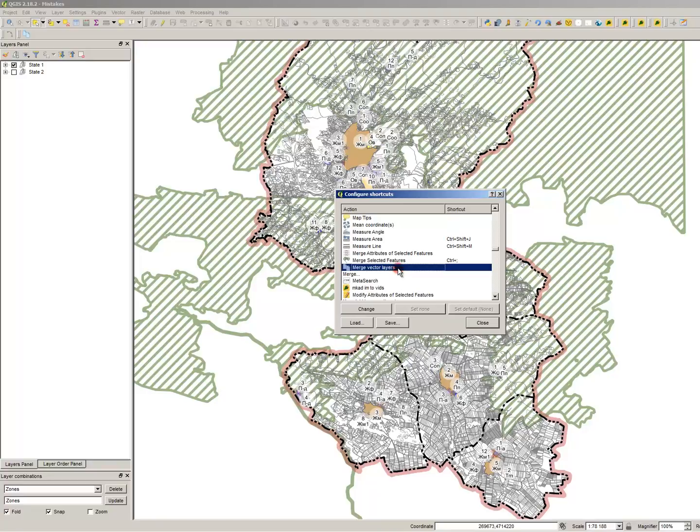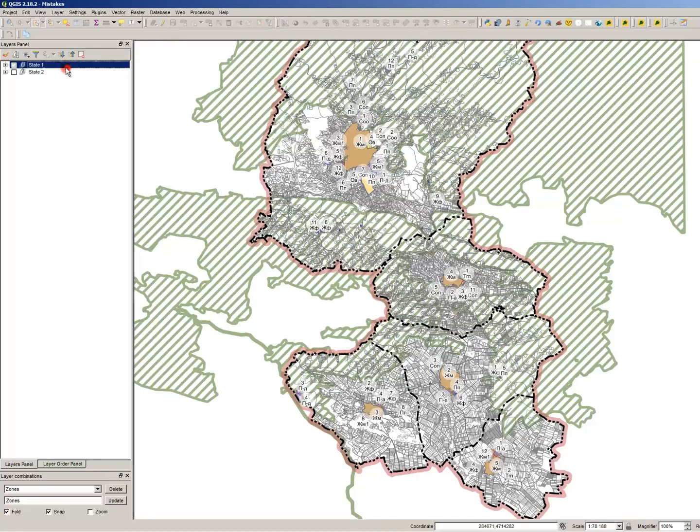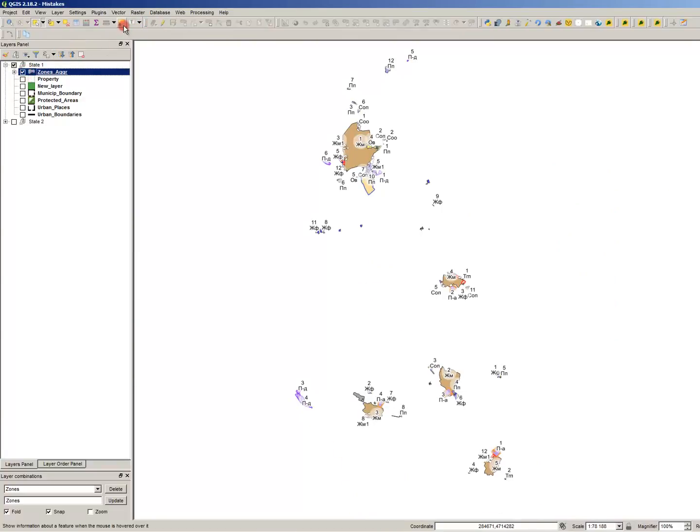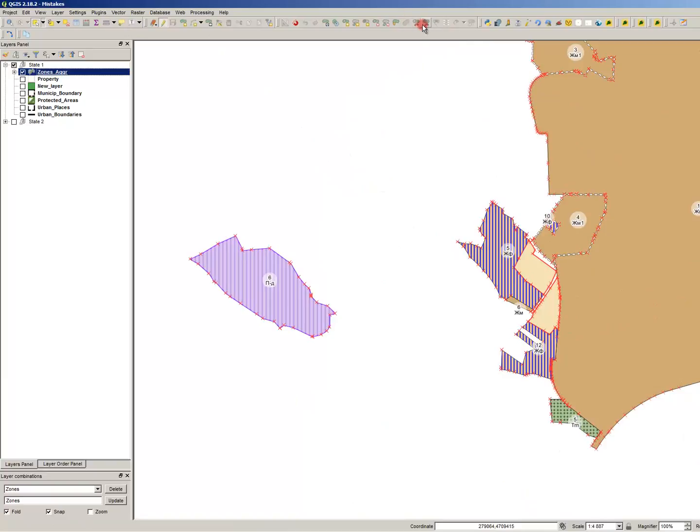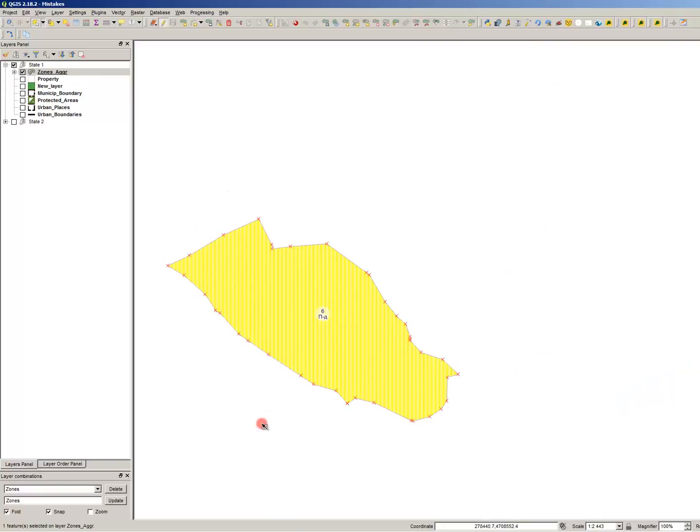Besides the merge command, you will need split features, also split parts. This is the scissors here. I will load the layer for editing. I will search for it. I rarely use the icons, but this one I use my shortcut Alt plus bracket, and it splits very quickly.